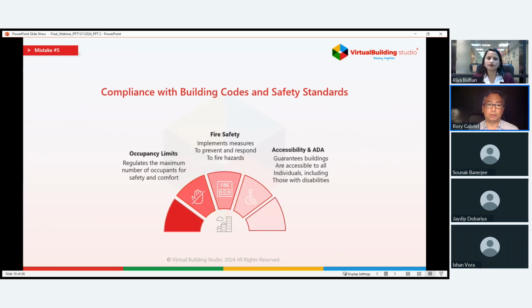So one common mistake could be occupancy, or really determining the correct classification of a space. Things like assigning classrooms to an educational use, or maybe they're part of a church, so it would be religious. Or if they're above the 12th grade, it's a B occupancy. Or maybe the occupant load of an assembly space, if it's in a restaurant, is less than 50, so we could use a B occupancy. These decisions will impact building heights, allowable areas, or maximum egress travel distances.